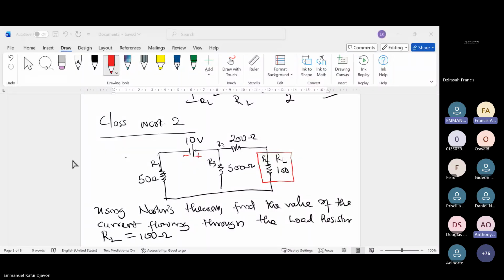See, you are multiplying it with the load resistance. The value of the load resistance is 100 ohms. You should check the load resistance value. It's 100. So you are multiplying 192.9 times 100. If you draw the equivalent, it's supposed to be 0.052 times 65.85. What final answer are you guys saying? We can't hear.